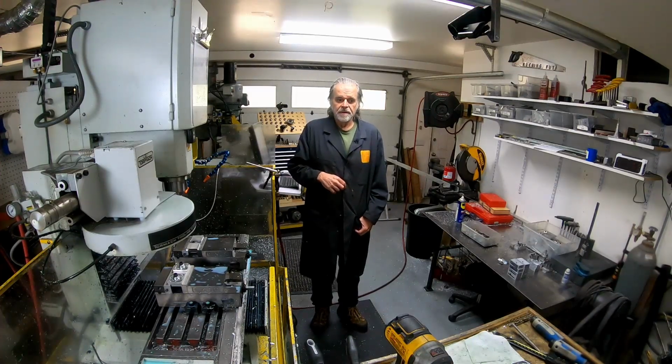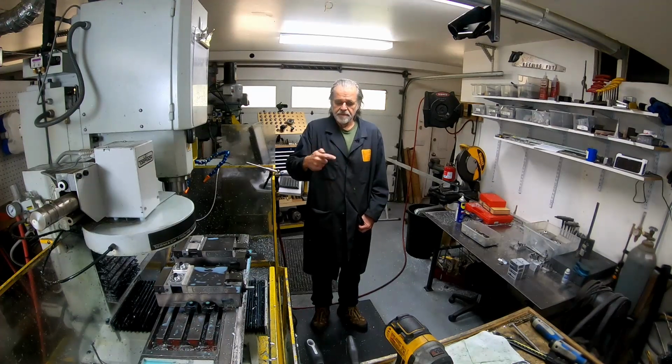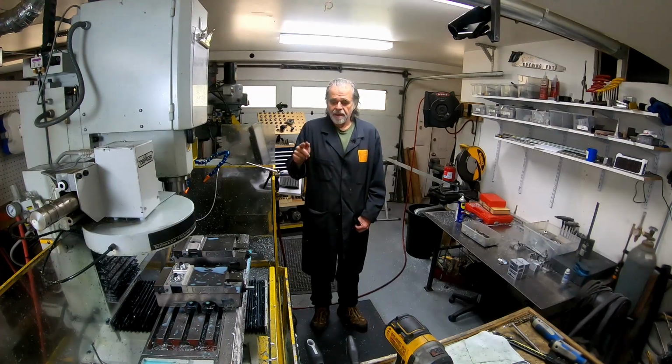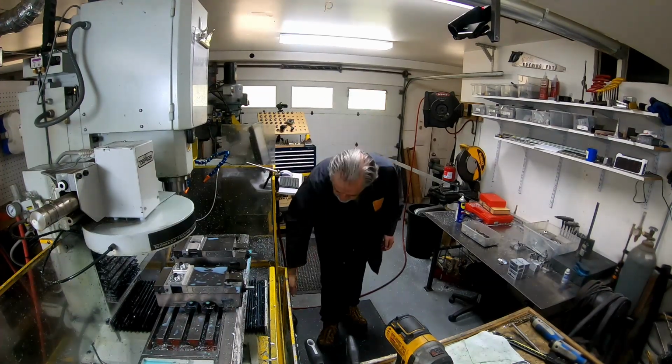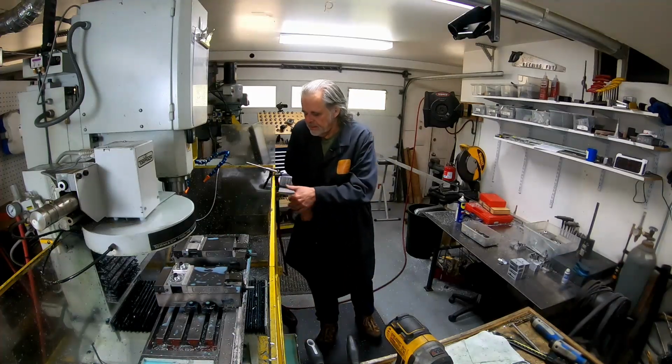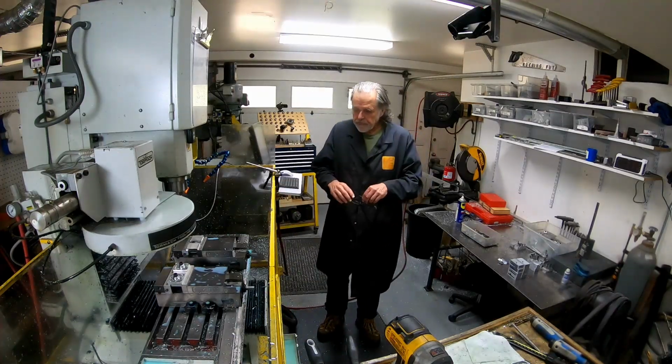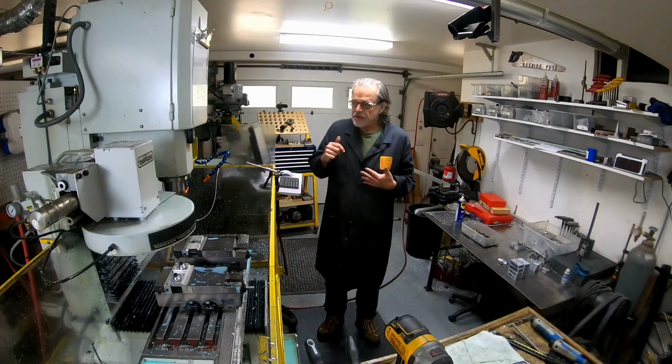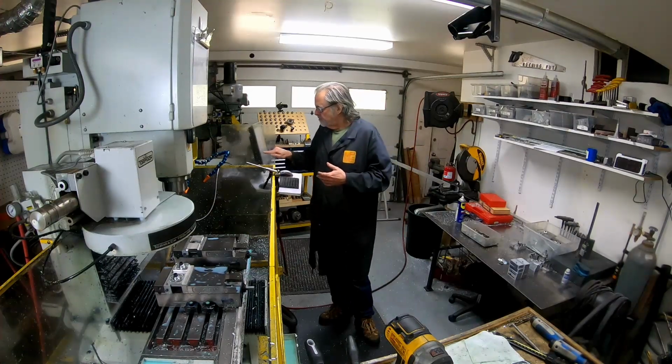And even though it's barely a CNC lathe and really doesn't work that well at all, it works well enough to do this work. And that's where I cut the O-ring groove, which needs to be pretty darn precise to make sure that the rollers are all the same diameter and that they all run true. So I'm going to go ahead and show the first and second operation in a 2-up gang.